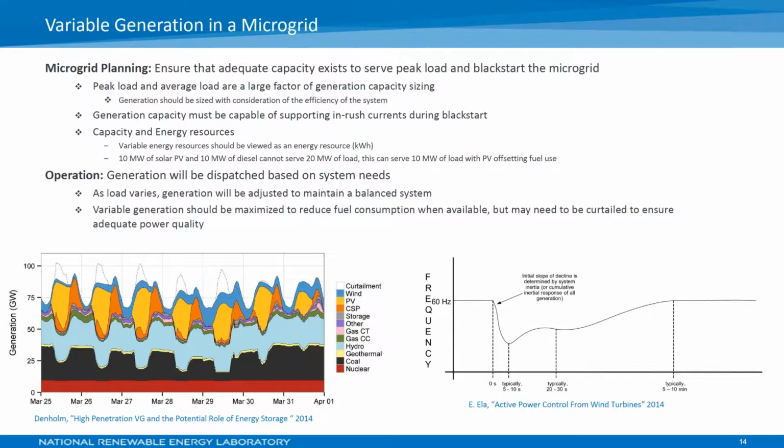And in operation, this is sort of the example on the bottom left. Wind and solar are varying, but also load is heavily varying. So you need energy storage, or diesel or fossil or natural gas generation, or hydropower, some other source that is more dispatchable to sort of complement the wind and solar and manage those variations throughout the day. And our load varies as well, so it's just another consideration of variation that you need to bring into the system. So I've typically always liked to think about power system planning, and this is how utilities think about it, in two steps: planning and actual day-to-day operation of the system.